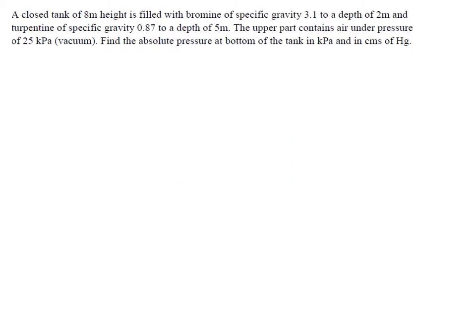The second problem is a closed tank of 8 meters height, filled with bromine of specific gravity 3.1 to a depth of 2 meters and turpentine of specific gravity 0.87 to a depth of 5 meters. The upper part contains air under pressure, which is 25 kilopascal vacuum.